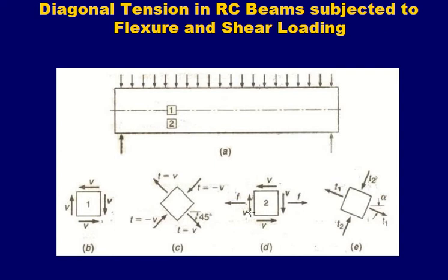Now, in the same way, I just want to remove these shear forces and find the principal plane and principal stresses. At the principal plane there is no shear force and only normal forces are acting. So in order to rotate that element, in this case you get exactly the same configuration of tension and compression, but the one thing that is different is that in this case you don't know the angle and you have to determine it by calculation.